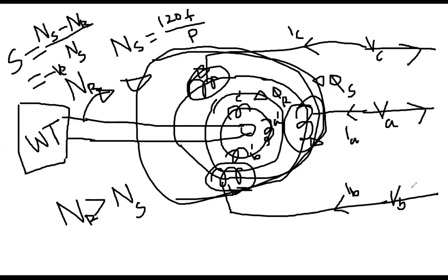Everybody see? Then the real power flow direction will be towards the grid when the slip is negative. And how is it possible? With the help of some source. If you can somehow increase the speed of the rotor, this means if you can make this condition, at that time you will call it a three-phase induction generator. And in that case, the active power flow is in this direction, but still there will be some Q flow towards the motor.